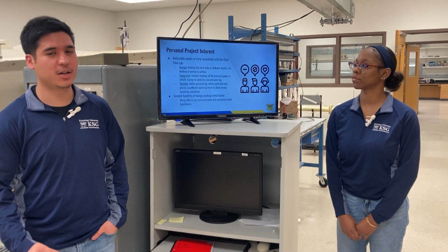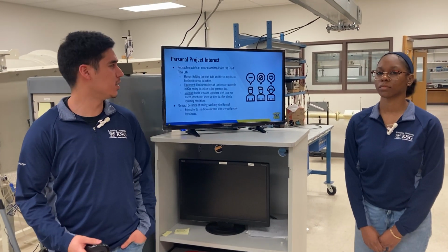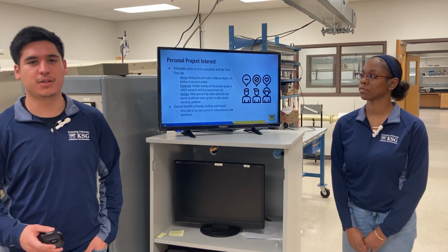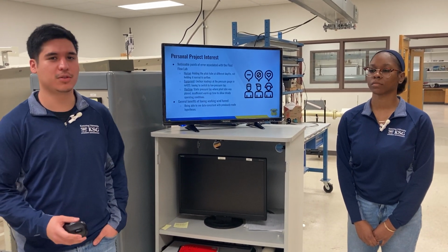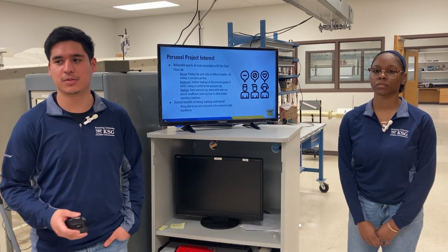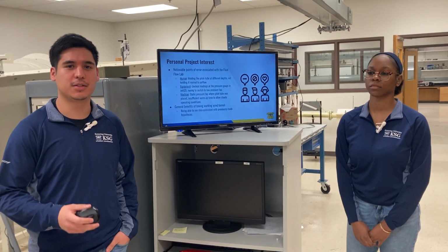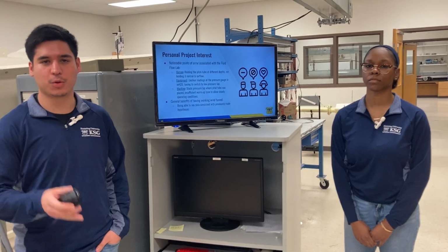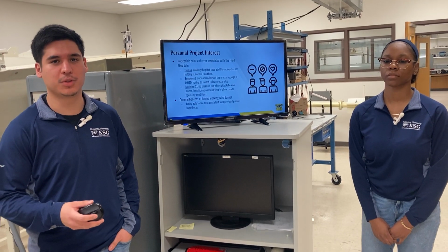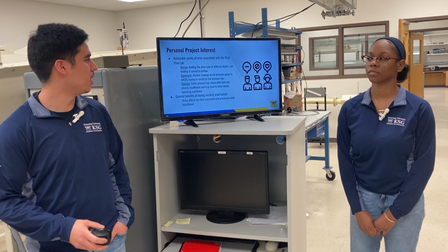So, like I said, our personal project interest was noticeable points of error associated with the fluid flow lab. First off was human error. Being that we were holding the pitot tube ourselves, we were changing the height data point to data point and not necessarily holding it normal to airflow. We were giving it a couple degrees of motion.